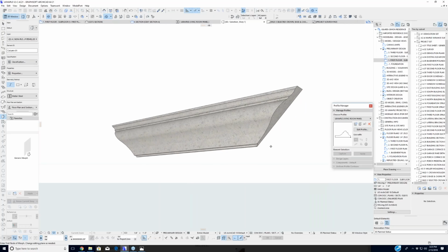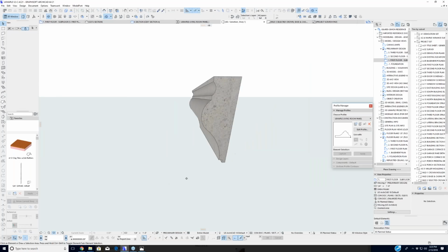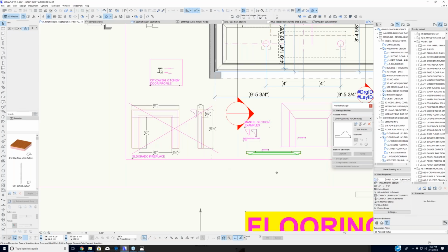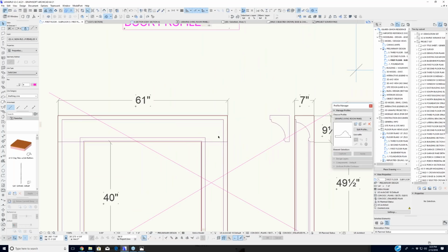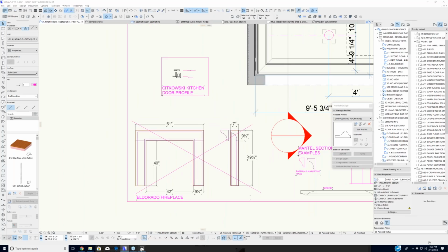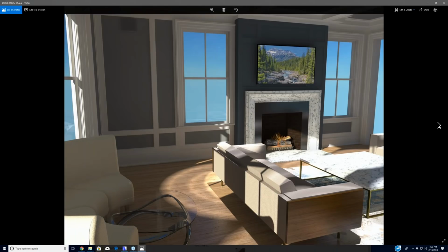Now, this was another sample they were looking at, but that right now is a morph, and this was a kind of a dry laid limestone, but you can certainly change the material to whatever you want. But that's how that's created, and it's mitered on the plan. So I'll miter that before I tilt it up. This happened to be cut and did a real return. And the reason I know that is from the website. When you look at the website of this fireplace up close, that's how they did that. So you do really need to spend some time just studying what you're going to model before you model anything.